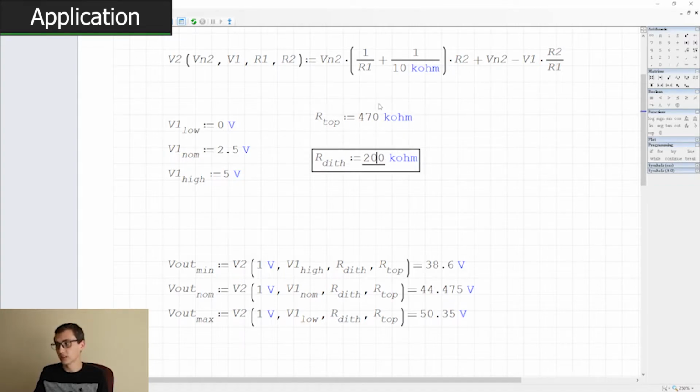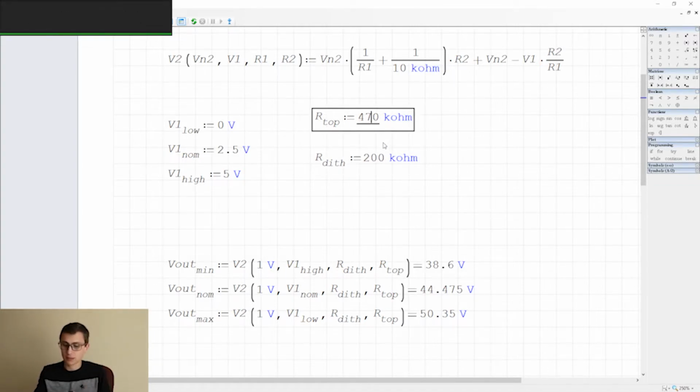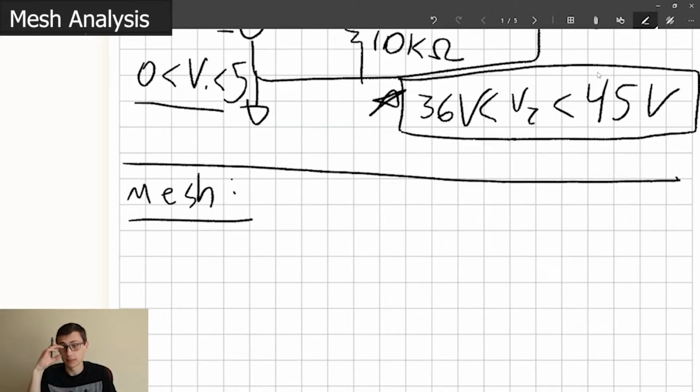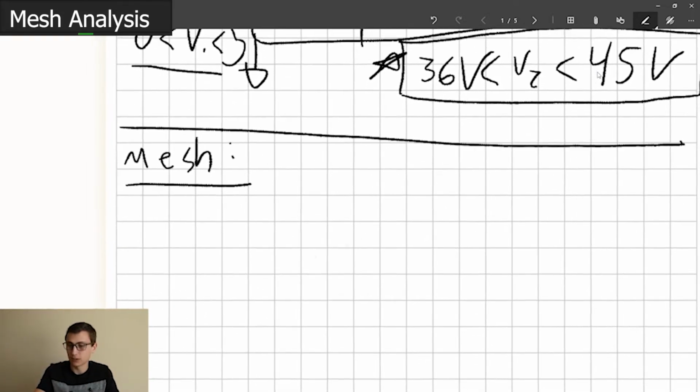This is a little bit too guess and checky for my liking, but you get the point. Before, we were applying Kirchhoff's current law, that's the sum of all currents must be equal to 0 at a node. Now we're going to apply his voltage law, which is saying that the sum of all voltages in one loop must be equal to 0. It gets a little confusing because when you're applying the voltage law, you're using current, and when you're applying the current law, you're using voltage. Just mental gymnastics galore. Balance in both loops, that means we've got to account for the current from source 2 when we're thinking about source 1.